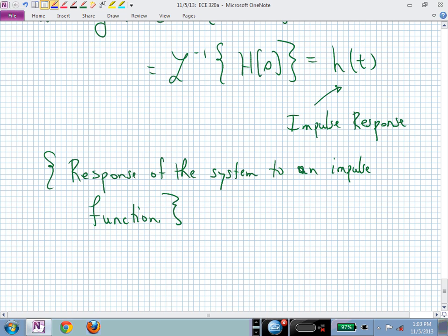That's how things can be solved sort of in the frequency domain. We said x of t was an impulse. Oh, we know what capital X of s is. That's 1. Then we plugged it into our expression in the frequency domain, and we learned how to find capital Y of s, and we can inverse Laplace transform that to get y of t.